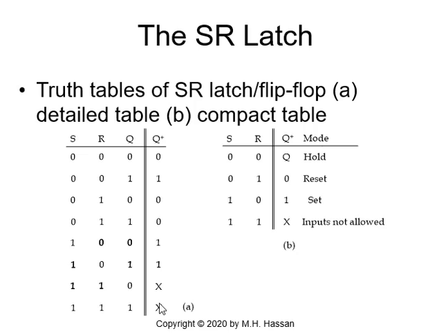And this is invalid because it's against the definition of the SR latch and SR flip-flop. Q prime has to always be the complement of Q, and Q plus prime has to always be the complement of Q plus. And this is the invalid state.